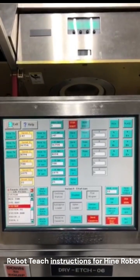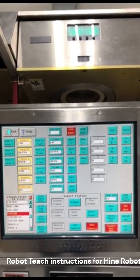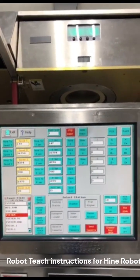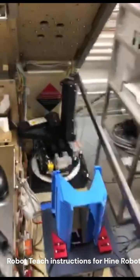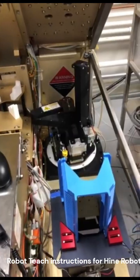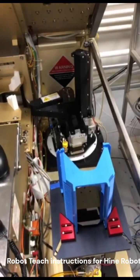In this video, I will teach you how to use Robot Learn to manually move the robot to a general position. Right now the robot is at home position, and I will teach it to find the first wafer in the cassette.